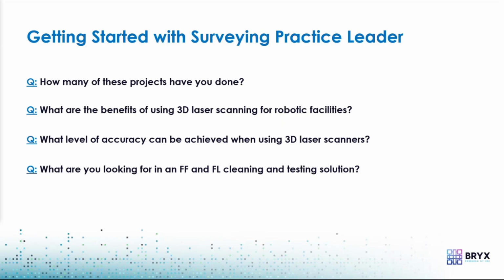We also run survey control through all our scan setups, so that we run digital levels for a cross check to make sure we're staying within accuracy where we need to be for these types of robotic floors. We can repeat 1.5 millimeter accuracy is what we've seen out of our system and the way we approach it. So it's usable.